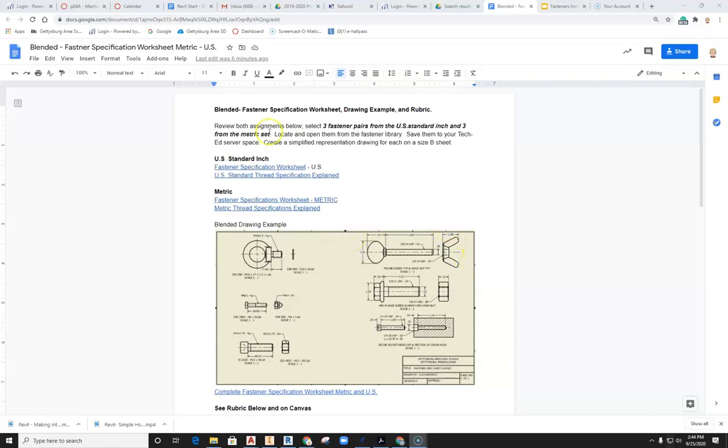Alright, in this video we'll talk you through how to work the blended Fastener Specification worksheet, drawing example, and rubric. So let's start here at the top. Review both assignments below. Select 3 fastener pairs from the US Standard Inch and 3 from the metric set. Locate and open them from the fastener library, and that's that library in Inventor. Save them to your TechEd server space. Create a simplified representation drawing for each on a size B sheet.